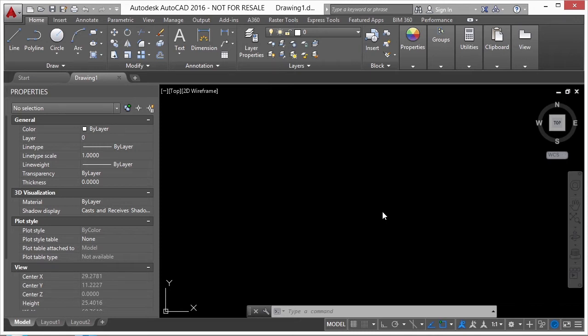But whatever text style and layers were used for that text, you're going to bring that into your new drawing as well, even a text style. So if you make a standard block to use them, in theory, that really shouldn't be an issue though. But there is a third method of text that you can use, and that is to import your text from a .txt file. Now, this gives you a few things the others don't. One is that there is no formatting involved that you have to deal with. There's no styles, no layers, nothing, just the raw text that you need. It also allows a non-CAD user to be able to type up the notes for you like an assistant.